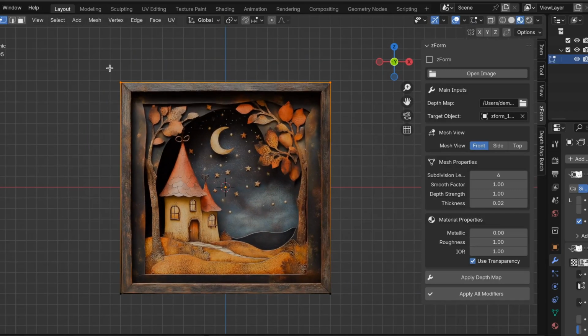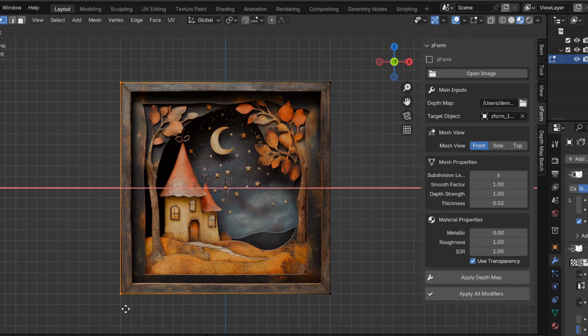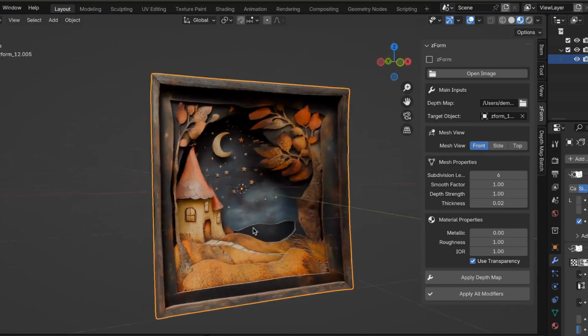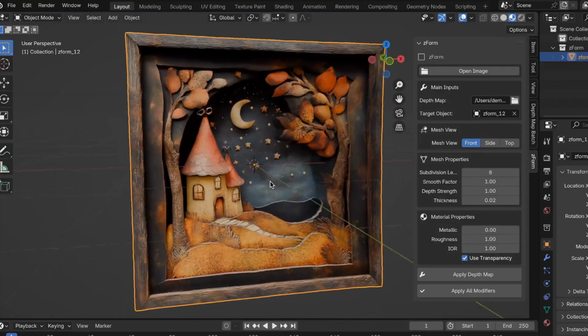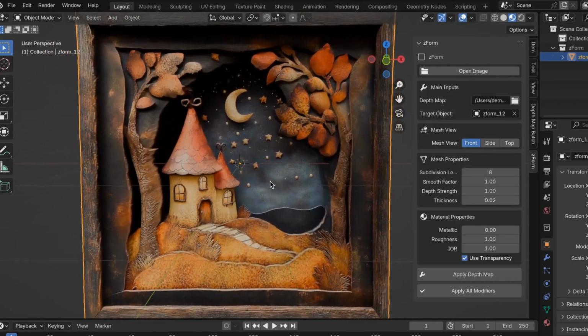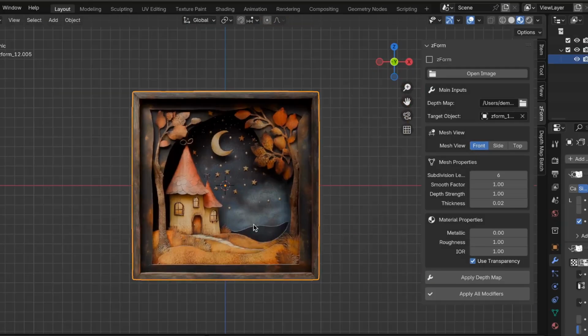And I might actually fix this on the left side too. Select the left two vertices and press GX like that. Then on the right side, maybe just a little bit, I'll do GX and like that. And then the bottom, GZ, and go up. And it looks a little bit better like that. You'll notice if you zoom in, it's not perfect. It's got flaws, but I think it looks pretty good. And I've enjoyed creating them. All right, let's try another one.